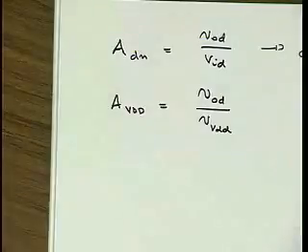Put it in series with your power supply, hook that whole thing up, and make it probably a volt, right? The ripple, the AC. But hook that thing to the input, to the supply of your chip, and you measure what comes out at the output. Right? And then you change the frequency and the amplitude and so on, you see how much it rejects that thing, or not, perhaps. Right?